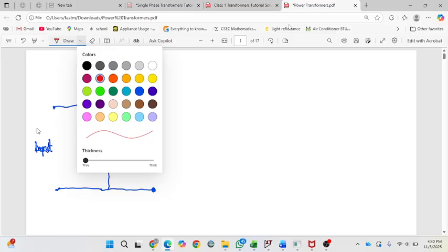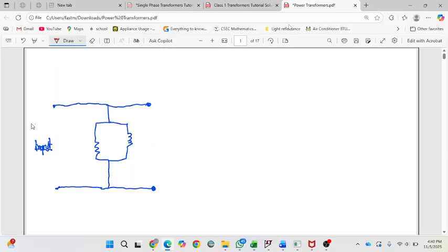The first way they could give it to you is in phasor form. So they will say V angle theta. For example, I might say 2 angle minus 2.3 degrees. So they will actually give you the voltage like this, or they will just give it to you like a flat value. Both of these mean the same thing, so don't get thrown off center if it gives you the voltage in phasor form.